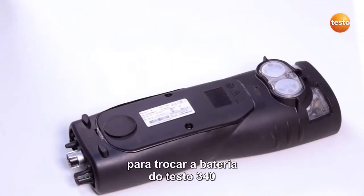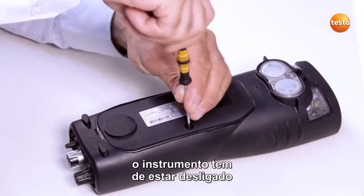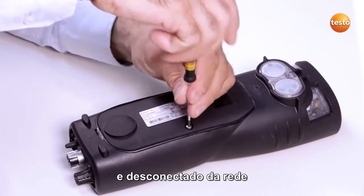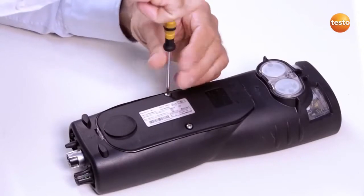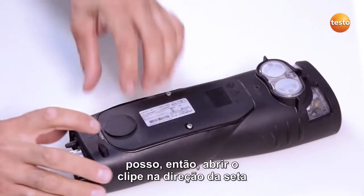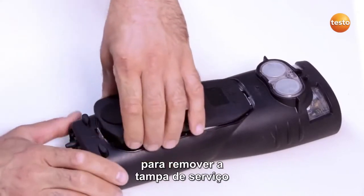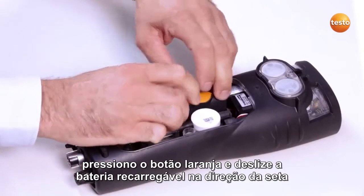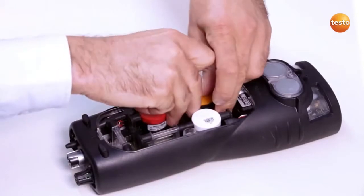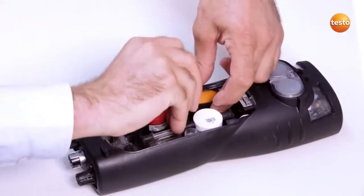To replace the rechargeable battery of the Testo 340, the measuring instrument must be switched off and disconnected from the mains. To open the instrument cover, I undo the screws. I can then open the clip in the direction of the arrow to remove the service cover. To open the battery lock, I press the orange button and slide the rechargeable battery in the direction of the arrow. I can now remove the battery.